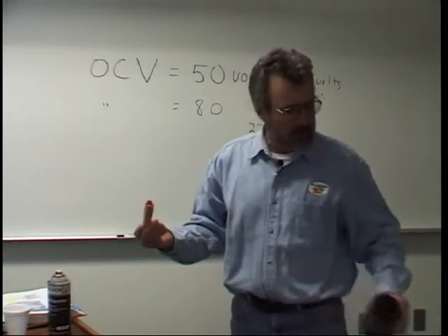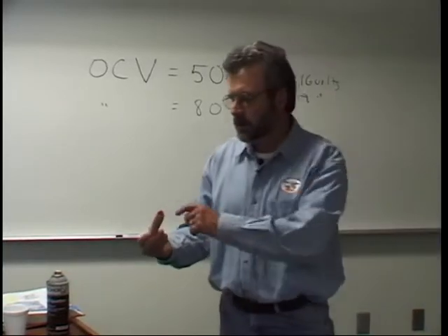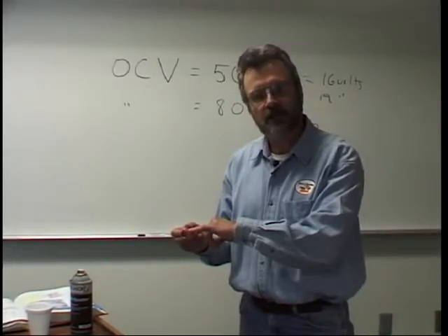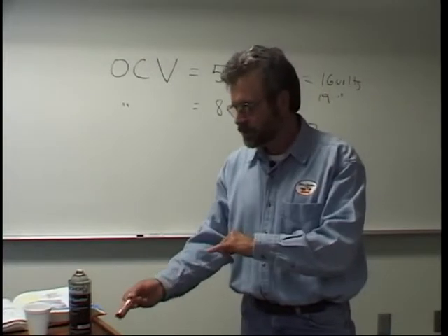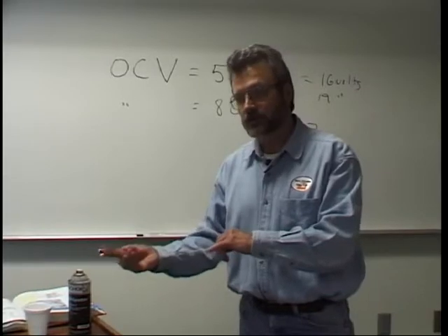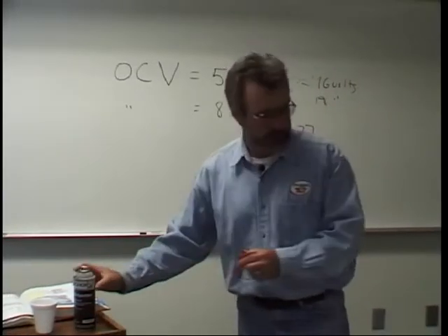If they get clogged up, which they'll do, they'll bridge from your contact tip to the cup itself. And if that happens and you touch it to metal, it's going to short out. So be aware of that. You've got to keep that clean, or else you're going to have problems with arc shorting as a result.